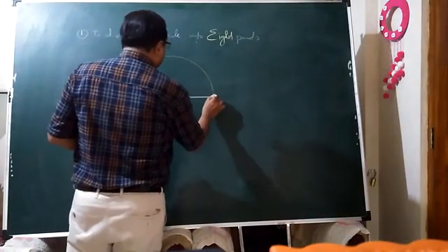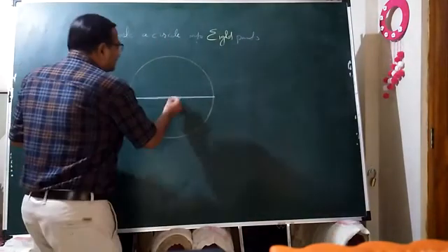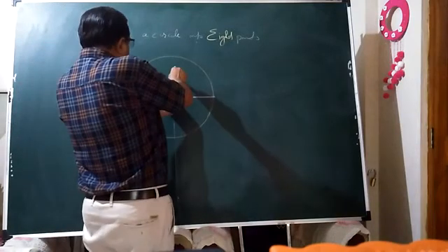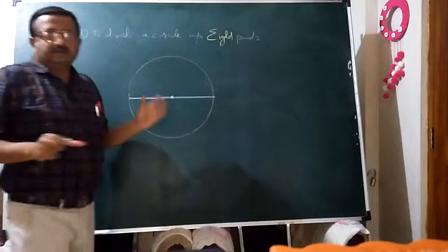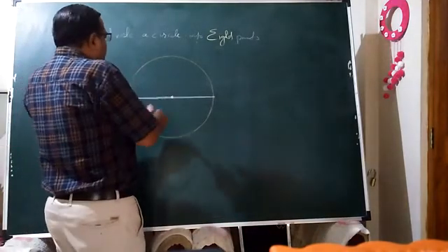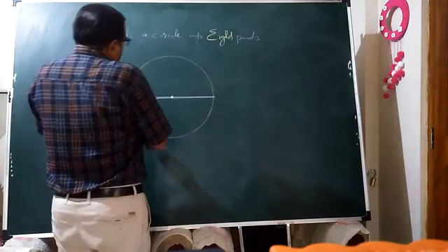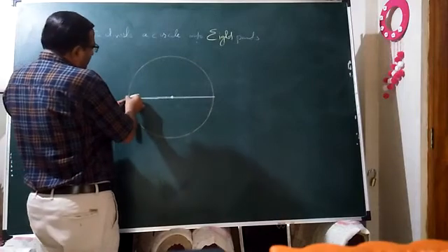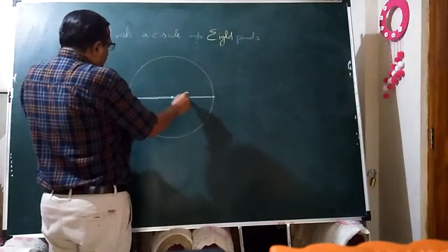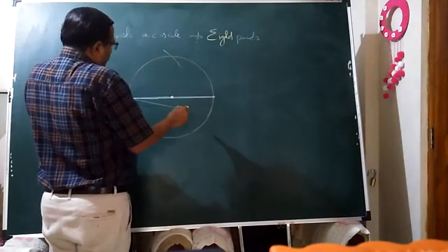Similarly, without using a protractor, you can get the vertical diameter line. And it is nothing but the practice of the second construction method of perpendicular lines. This point is on the given line, and from this point we have to construct a perpendicular line. Or else, in this way also you can proceed. These are the two extremities of the given line. Pick more than half of the distance in compass and get one arc on the above side in this way.